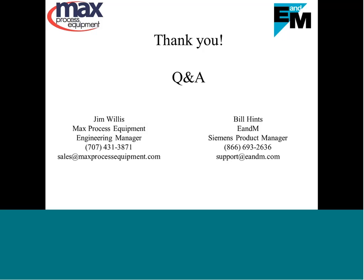PID, usually when we talk about PID, there's two different flavors. There's what's called velocity PID, and there's positioning PID. So velocity would be if we're doing a PID loop that's going to control the speed of a motor. That's a velocity loop. And what that means is when you actually reach set point, you want to maintain the output to keep that motor spinning.